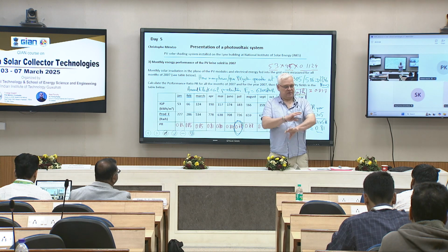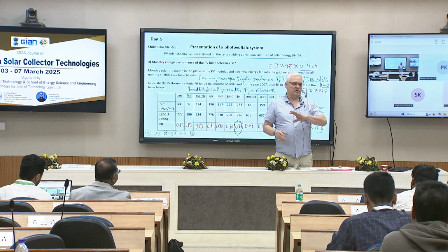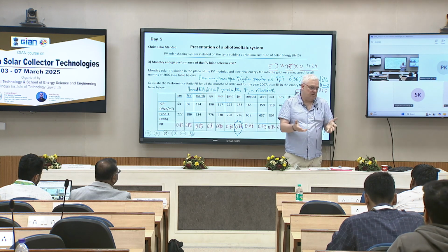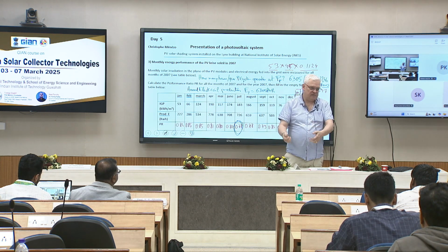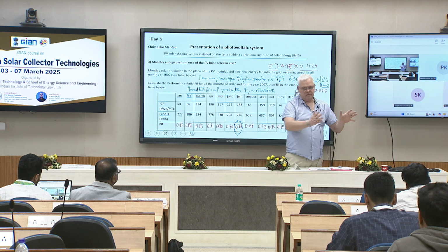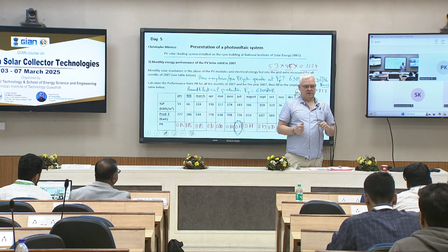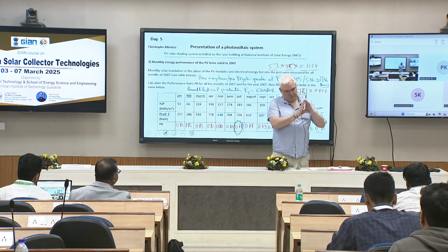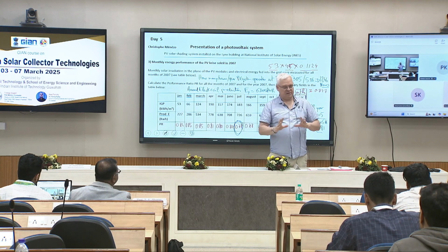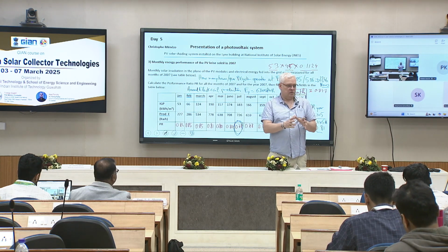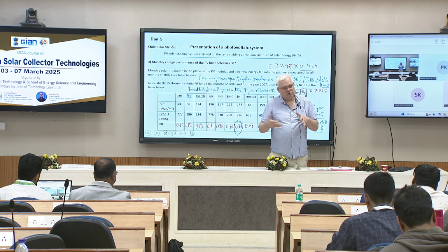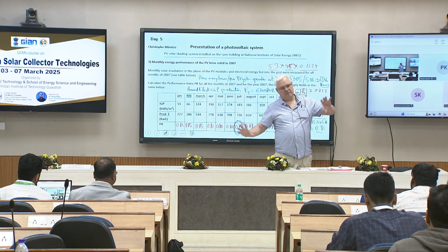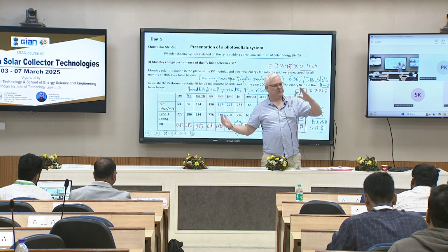The performance ratio doesn't consider the efficiency of my panel. You are buying a panel, you have an efficiency, so you can't increase that except if you change your panel. So the performance ratio is, when it is integrated, what you should expect versus what you really have at the end. It is the efficiency of my PV system.